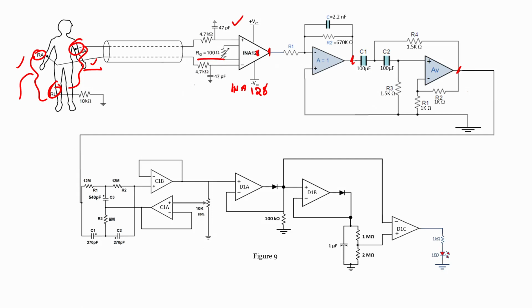Now when we see the output at this particular point, since it is not a processed signal and we have only done the amplification stage, we can see the raw ECG signal, an amplified version of it. But if you recall the discussion, as the professor discussed in the class, the raw ECG signal is always prone to a lot of interference and noise from other signals. Those are our power line interference, baseline wandering, and motion artifacts, all of which will be observed at this point.